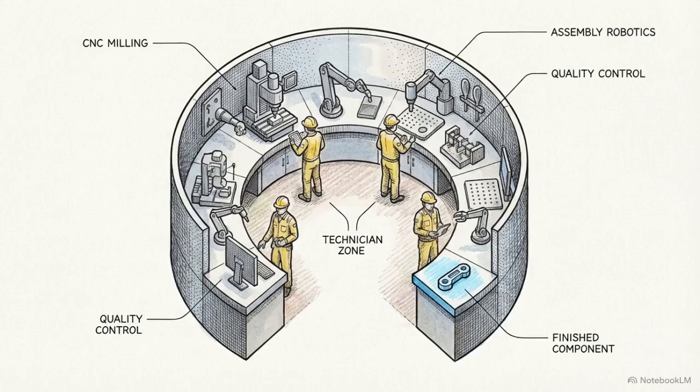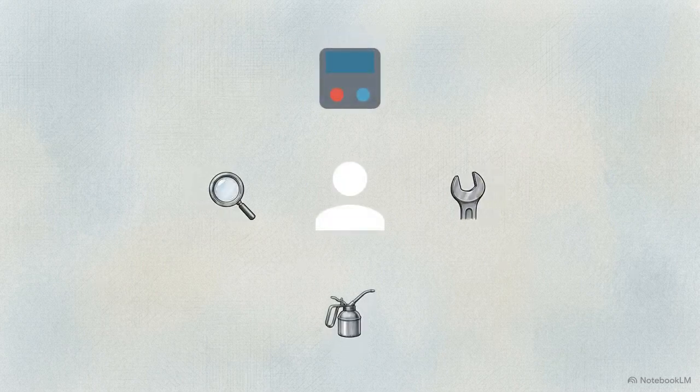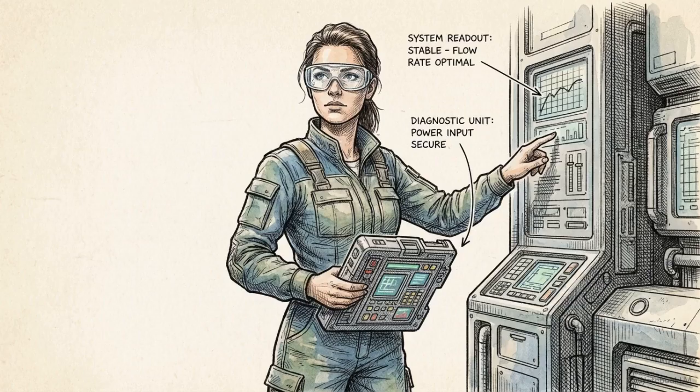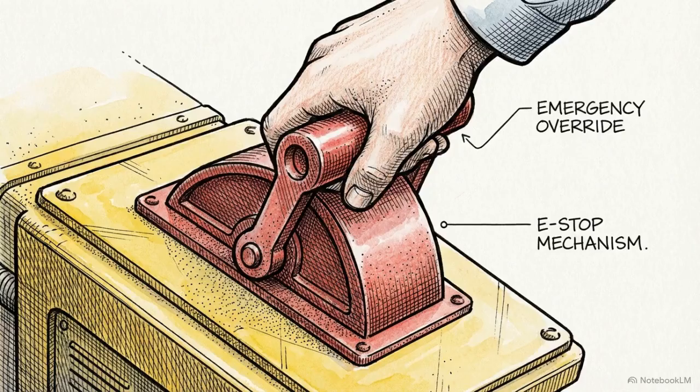Instead of moving between specialized departments, each semicircular cell functions as a self-contained miniature manufacturing plant dedicated to producing a given product or product family. Operating a self-contained cell requires multi-skilled labor. Workers must be able to operate all machines and simultaneously perform support tasks, such as machine setups, preventive maintenance, and quality inspections. Multi-skilled teams require empowerment. Under a JIT system, workers have the authority to completely stop production to correct a sudden problem, rather than pushing a defect down the line.